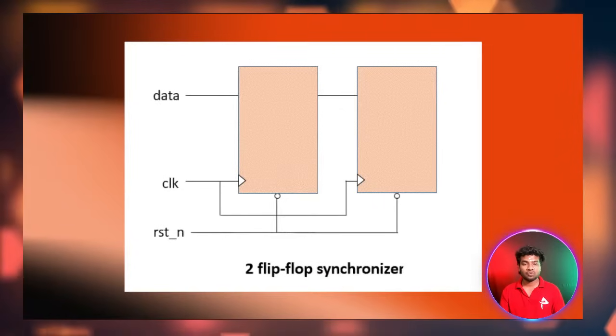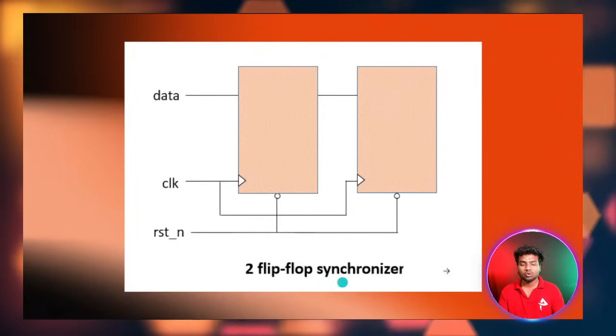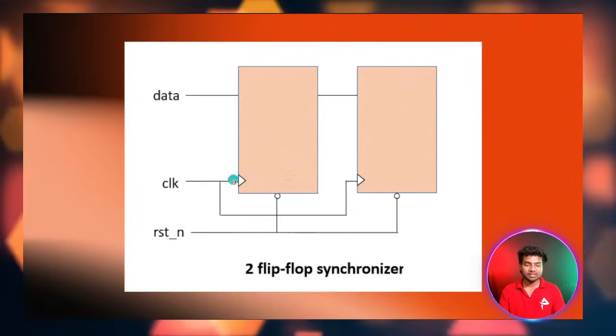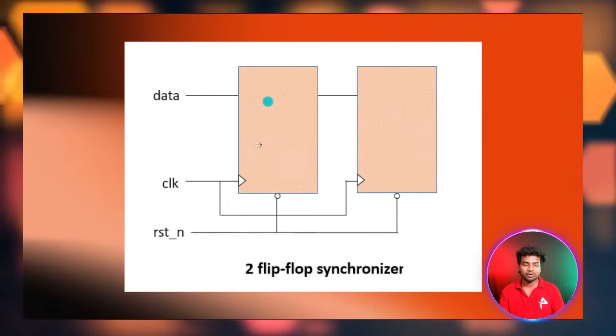So to neglect that, to remove that, you can use the two flip-flop synchronizer. You can see here that in the first clock cycle it will get the data, and it will store it for one clock cycle.